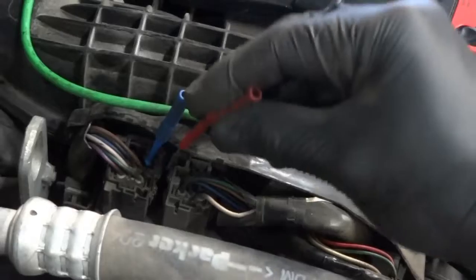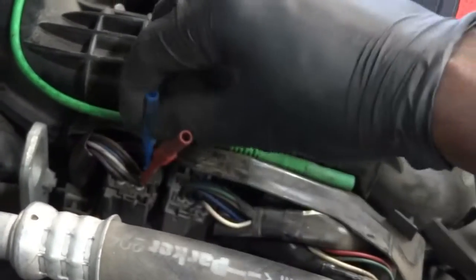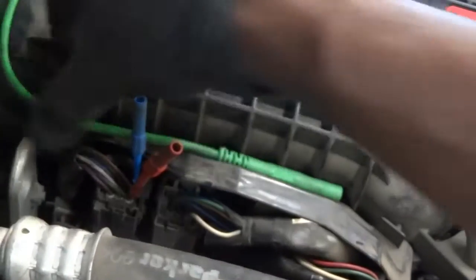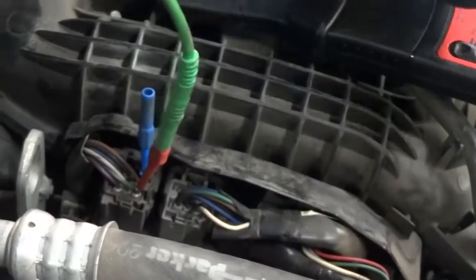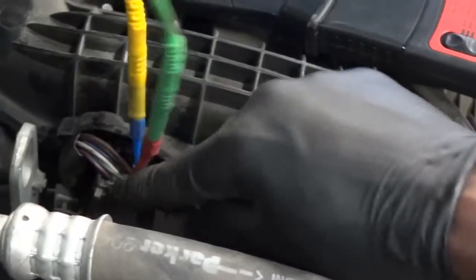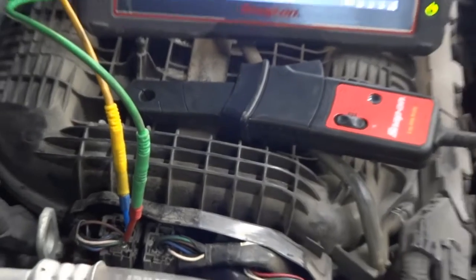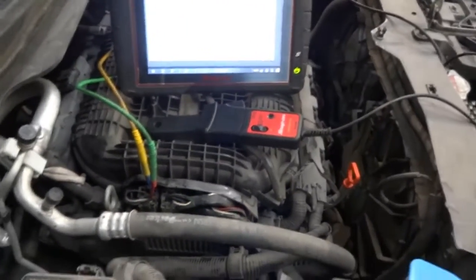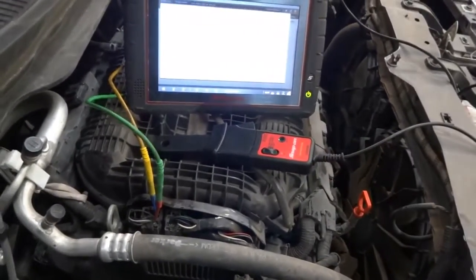So I'm doing this just to compare the voltage waveform of the injectors we just tested and one of the injectors on bank 1. So we got this connected. Let's connect this one. Okay, so I'm gonna find a way to clamp my amp clamp around this brown wire, and then we'll see what kind of waveform we're gonna get on the lab scope screen. So I'll get this amp clamp wrapped around the brown wire, and then I'll bring you guys back up.